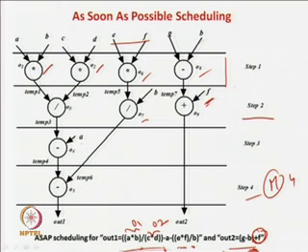Now if you look at it, output 2 is already generated. So, this part is over. Then you have to observe O4, that is the subtraction operation. This cannot be done in time step 2, because the predecessor of O4 is O3, and O3 has to be done before O4. As O3 has already been scheduled in time step 2, in time step 3 we can schedule O4. Similarly, the last one, this subtraction operation O5, can only be done in time step 4, that is 3 plus 1, because for O5 we have two predecessors, one is O7 and the other is O4.